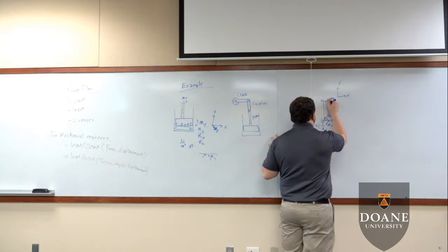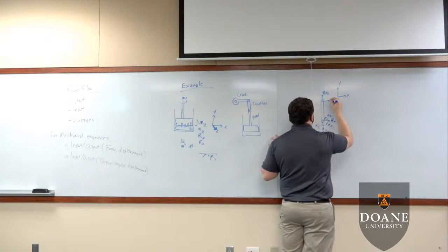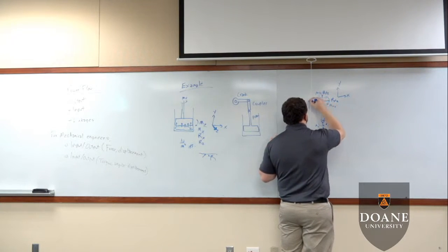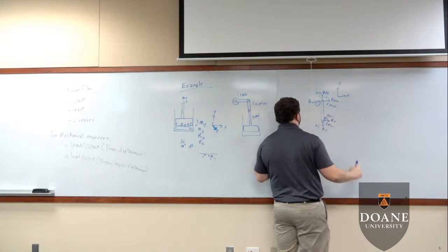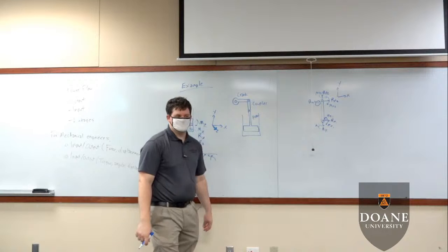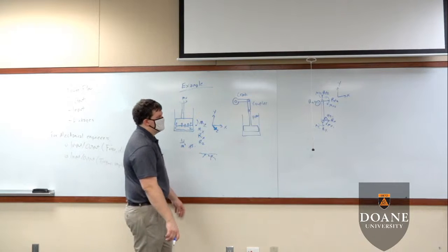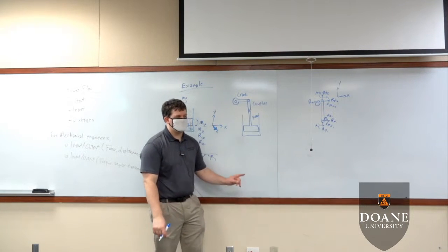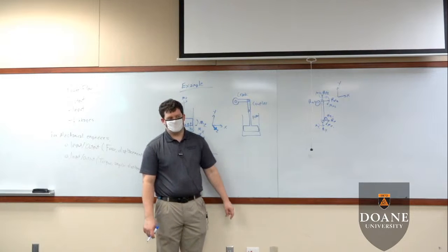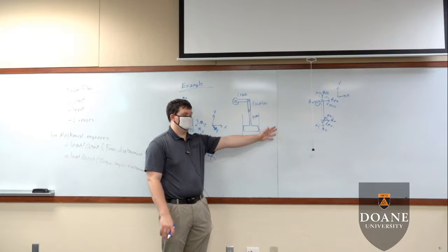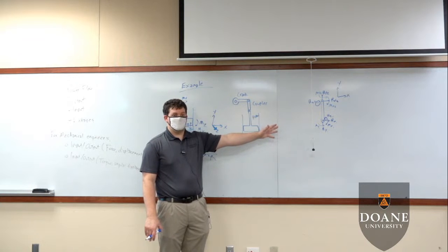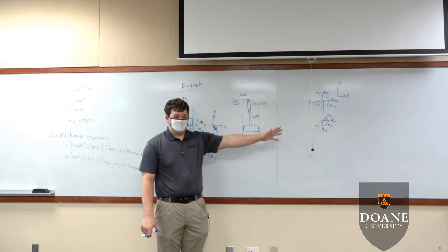And we can similarly apply the same forces up here. Our x2, our y2, mx2, my2, and RZ2. 5 forces. Well, 3 forces and 2 moments. Okay? Those are all of the possible forces and moments that can be carried by a revolute joint. Okay? Any questions on that? Those are all the possible forces we can have. No questions?